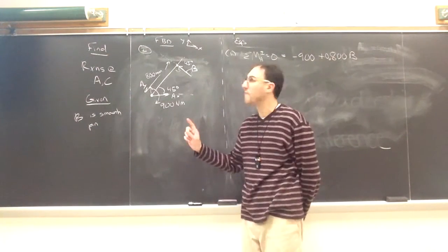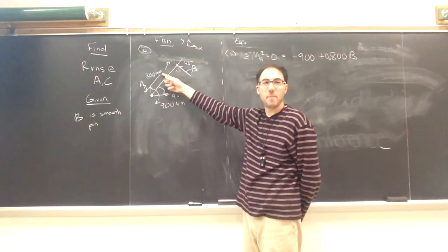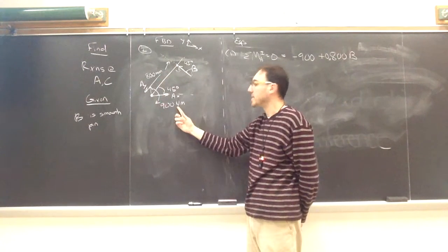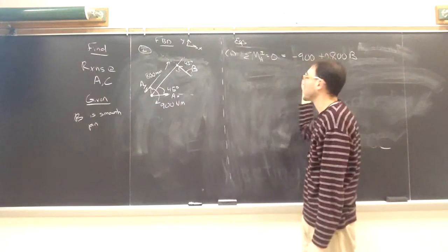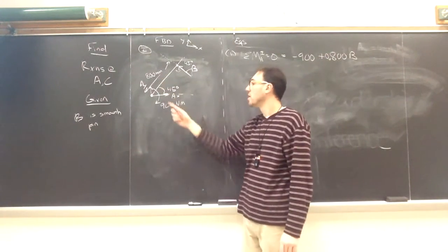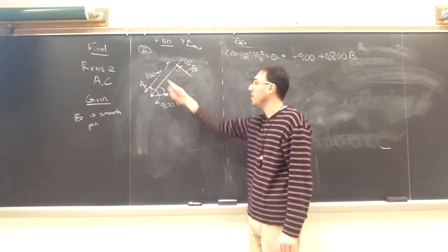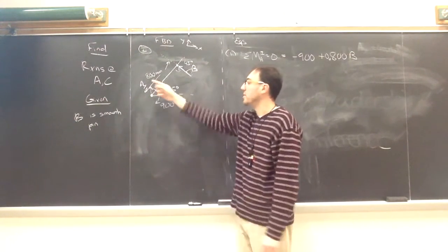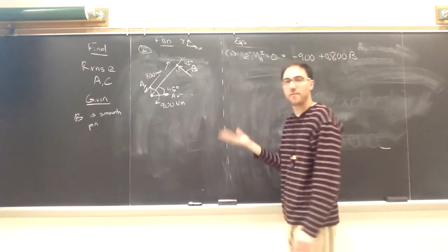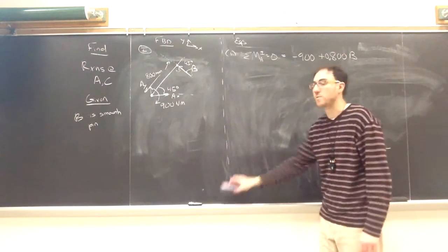This is where we have to be careful. This is given to us in millimeters, which is okay, but this is given in Newton meters. So either everything on this line has to be in meters, so it matches this, or everything in millimeters, which I would have to then change this into millimeters. So instead of the 800 millimeters, I'll just convert it into 0.8 meters.